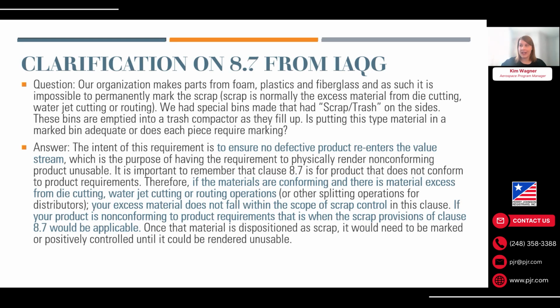It is important to remember that 8.7 is for product that does not conform to product requirements. Therefore, if the materials are conforming and there is material excess from die cutting, water jet cutting, or routing operations or other production operations, your excess material does not fall within the scope of scrap control in this clause. If your product is non-conforming to product requirements, that is when scrap provisions of clause 8.7 will be applicable. Once the material is dispositioned as scrap, it would need to be marked or positively controlled until it can be rendered unusable.